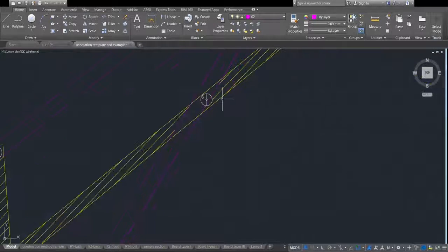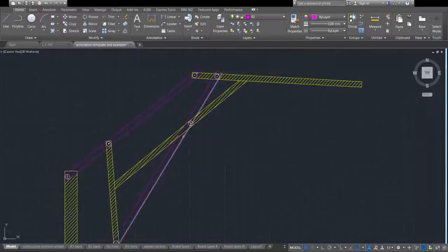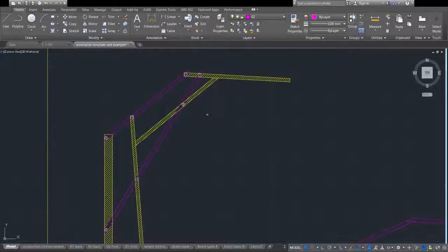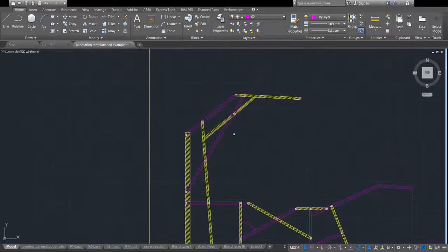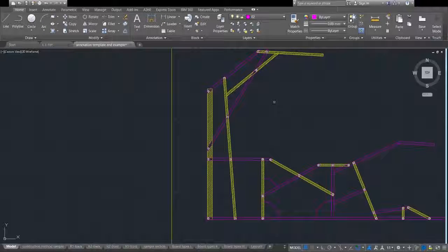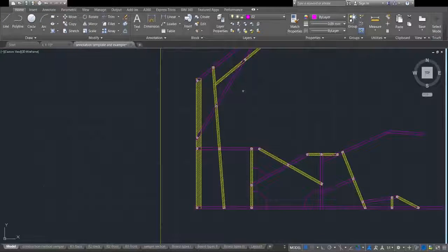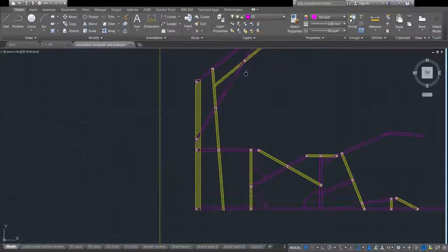We also don't need to show the angle between these two, because that would only be useful for placing this one. If you want to include the angle, though, it's not an issue, and in fact, more information provides the builders with additional information to make sure that stuff is being placed correctly. So if you're not really sure if you should include something or not, you should include it.